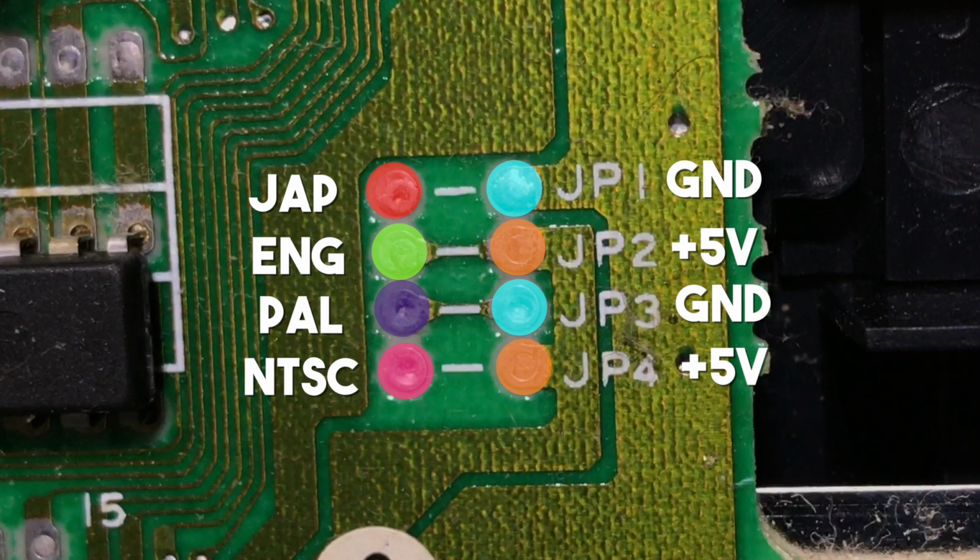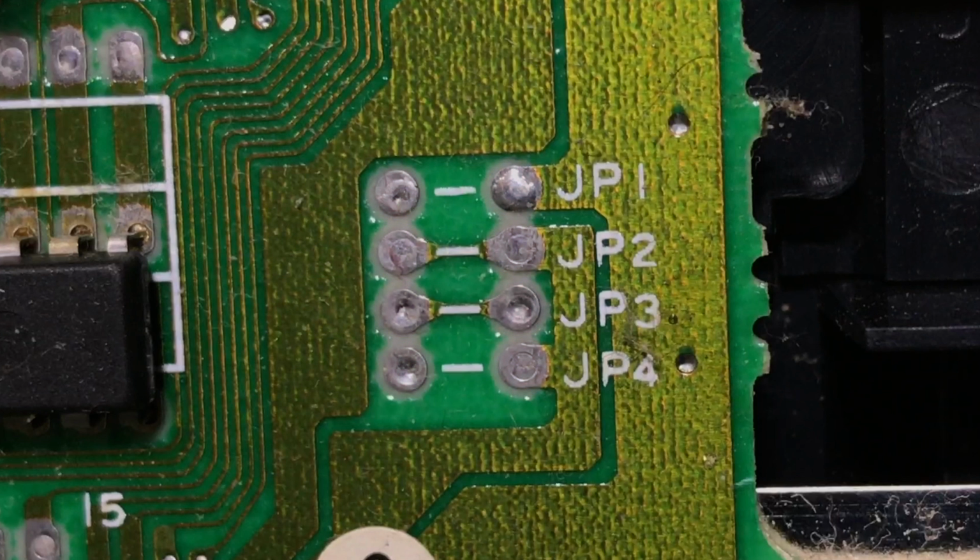In some cases there may be a capacitor over the JP1 pads, which you should remove by gently heating up the pads where the capacitor's legs meet the circuit board while carefully pulling the capacitor itself. There are horizontal white lines connecting the left pads to the right ones, and you'll need to use your hobby or Stanley knife to cut the traces linking the JP2 pads and the JP3 pads as well.